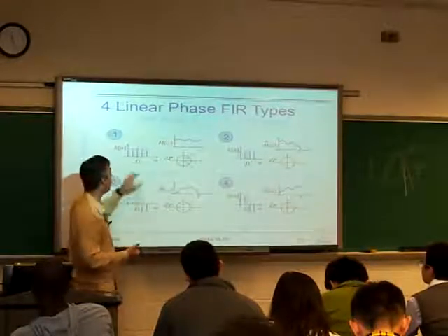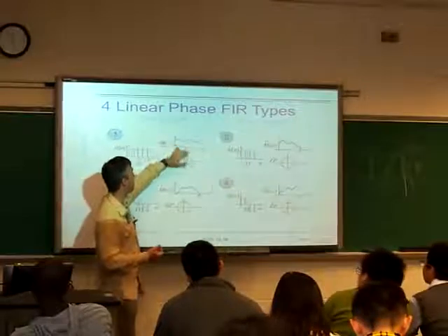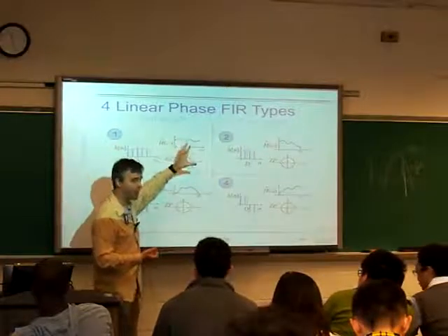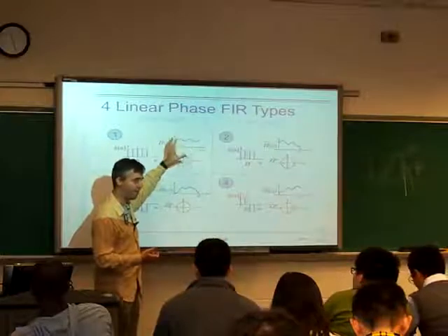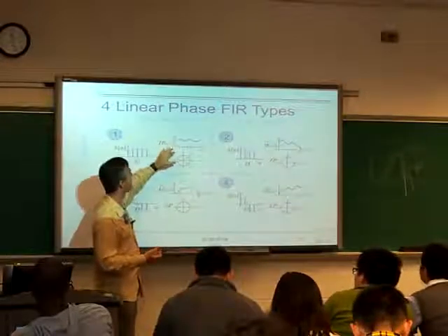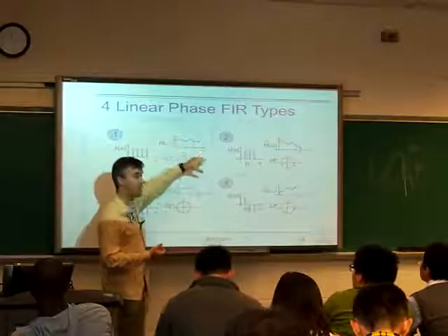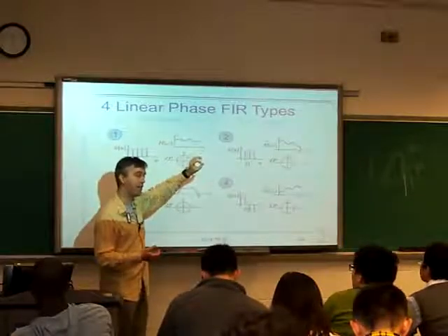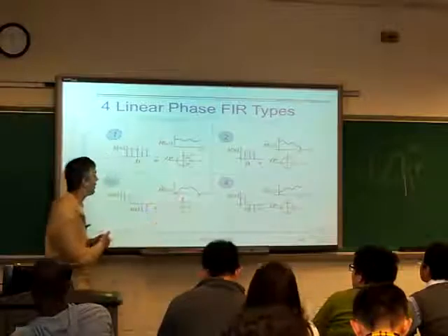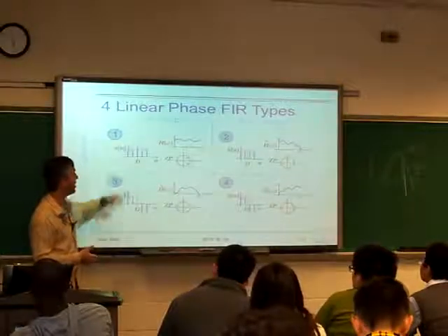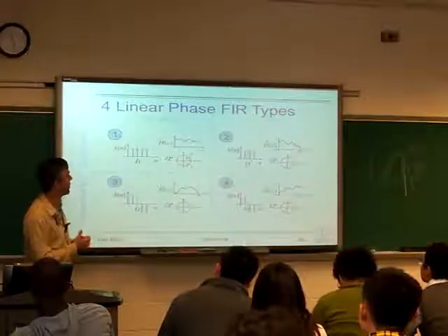If I do have a full set of cosines, well, cosines are always going to be 0 phase, but then magnitude responses are always going to be symmetric. Magnitude responses for real systems are always going to be symmetric. So that's not a big constraint. But then we can make whatever shape we want. It's just the level of detail is going to depend on how long we make that filter. So it's a very, very general set of filter responses we can make.